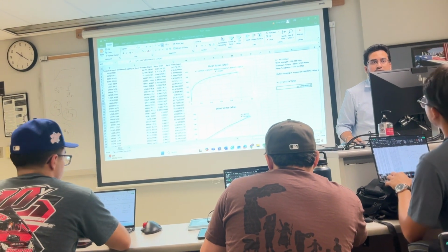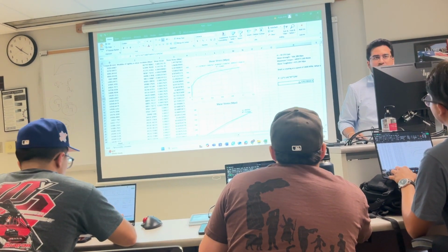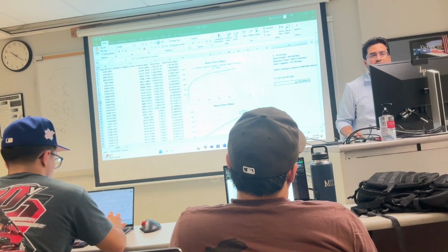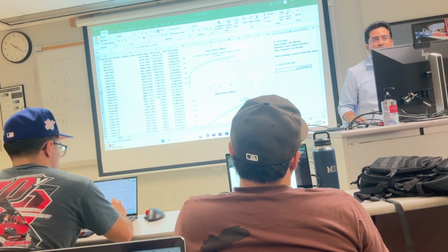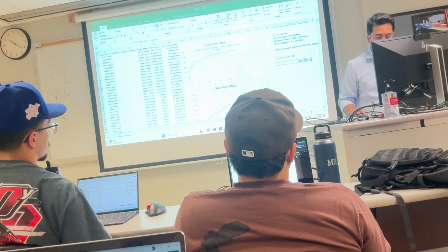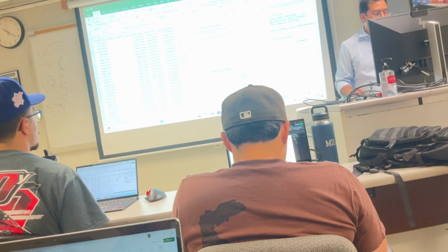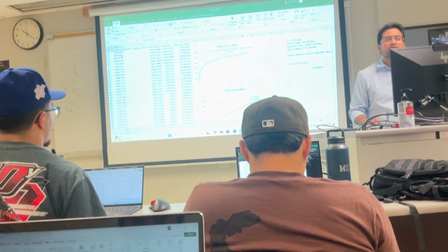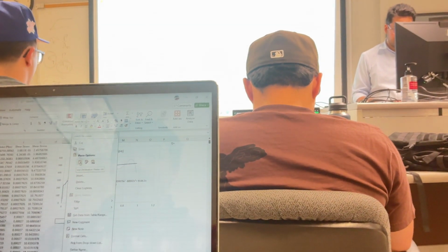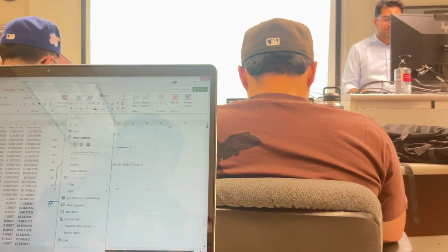Divided by 60, right? Yeah, I got that value. And then you put the max torque and divide it by 1,000 to get Newton mm, right? No, that is already in Newton mm. This data you get from the D column, and column D is already in Newton mm. Divided by 60. So it's going to be that much power.